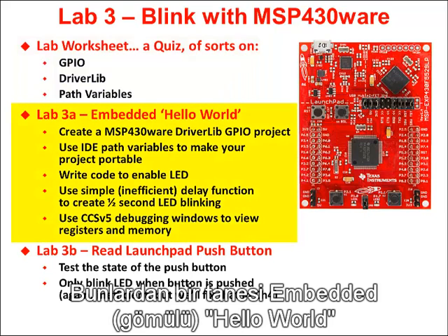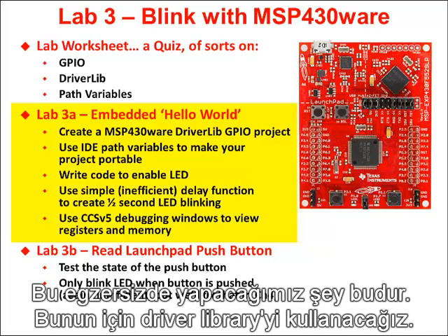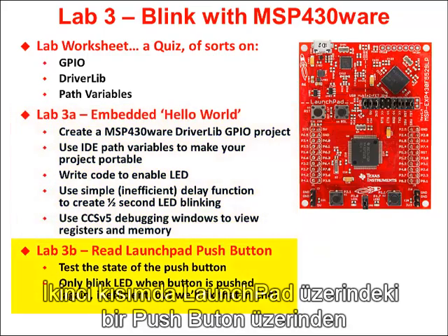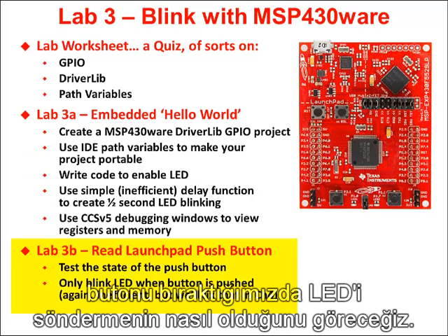The two actual exercises we're going to do: first, an embedded hello world. The hello world of embedded systems is blinking an LED. So that's what we're going to be doing here. We're going to do it using driver library. Then the second part is going to be reading one of the push buttons from the LaunchPad. So we'll get a chance to see that. When we see the button pushed, we'll light the LED. When we see the button not pushed, we'll not light the LED.